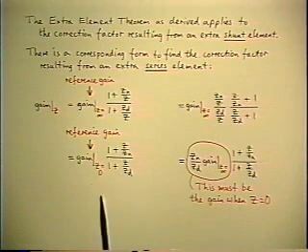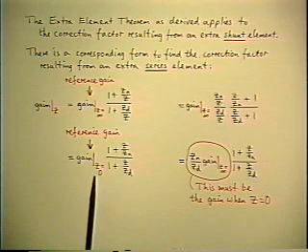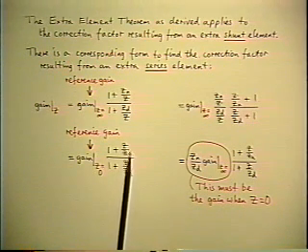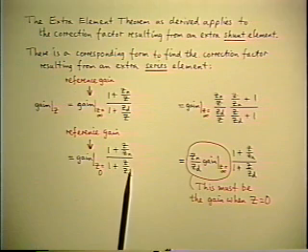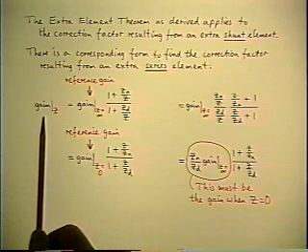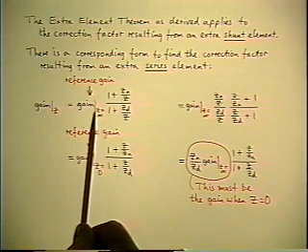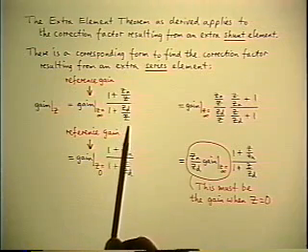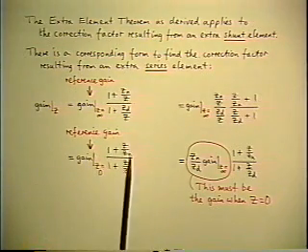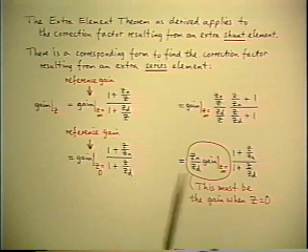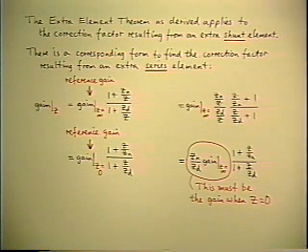So you can express the gain of the system in terms of the gain when frequency is 0 and a normal pole in 0, or you can express the gain of the system in terms of the infinite frequency gain and an inverted pole in 0. So the algebra is identical. The variable is now Z instead of frequency. That's all. So this relationship is not surprising.